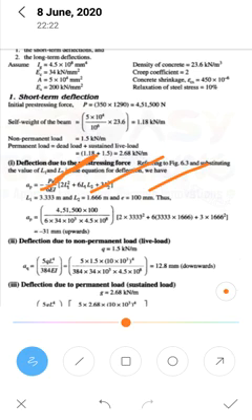You use this formula: Δp = minus P e divided by 6EI into (2L1 square plus 6 L1 L2 plus 3 L2 square). Here you insert the L1 and L2 values, and finally Δp will be minus 31 mm. You got a minus value, so the deflection is in the upward direction.